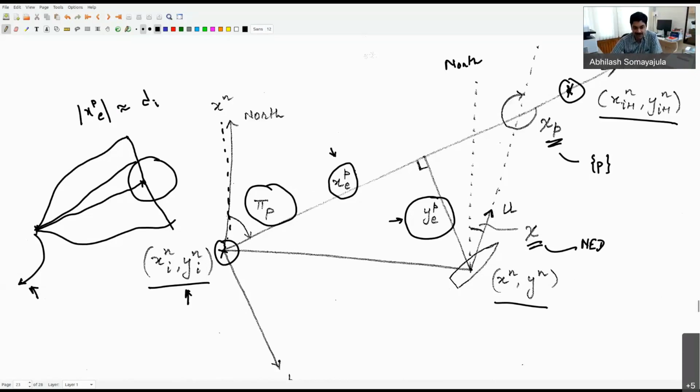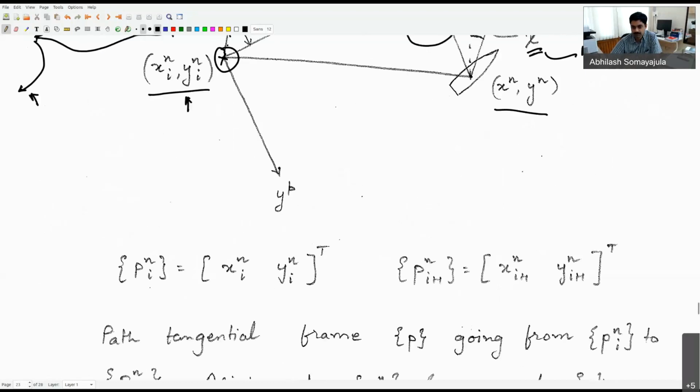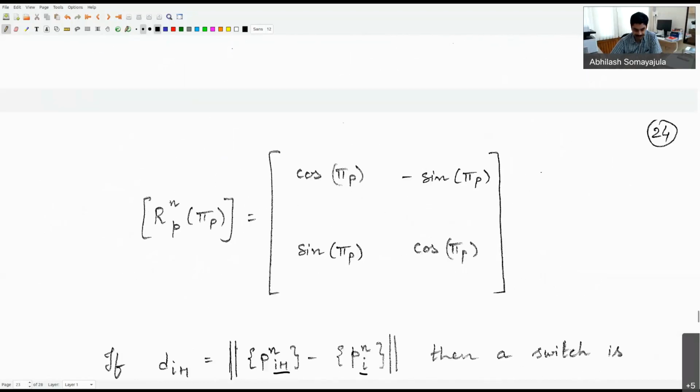Okay. So when the along track distance is equal to the distance between the waypoints, then you would have at least reached horizontally in the same direction as your next waypoint. So it's not an error per se, but because of the cross-track error being defined in that manner, the name has stuck around. Actually it's not an error. It's the distance, how much you have moved along the line connecting the two waypoints. That's what it represents, essentially. Okay, sir. Okay, all right.